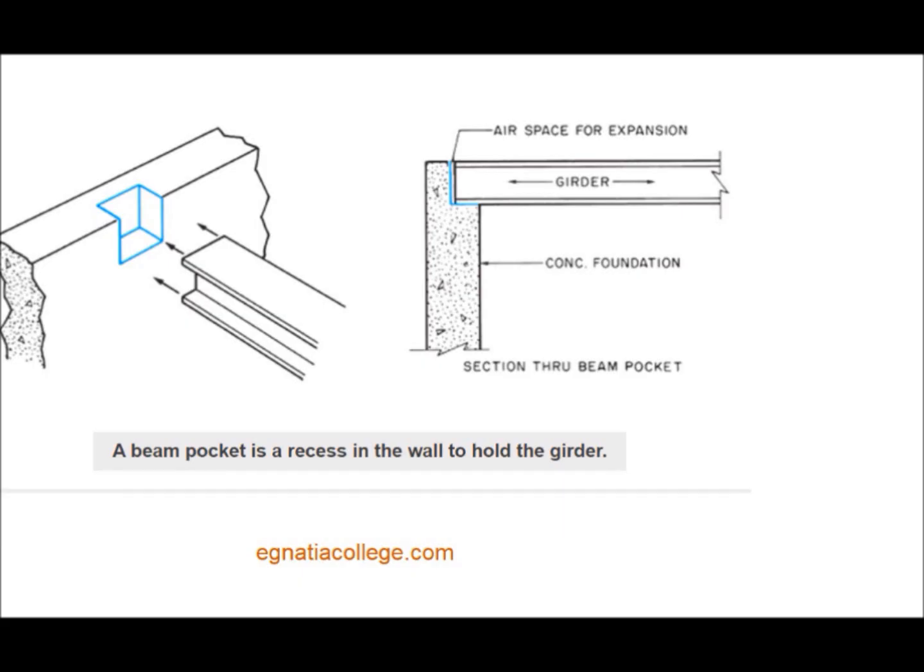If windows are to be included in the foundation, the form carpenter or mason must provide openings of the proper size. The locations of windows should be dimensioned on the foundation plan. The sizes of the windows may be shown by a note or given on the window schedule.